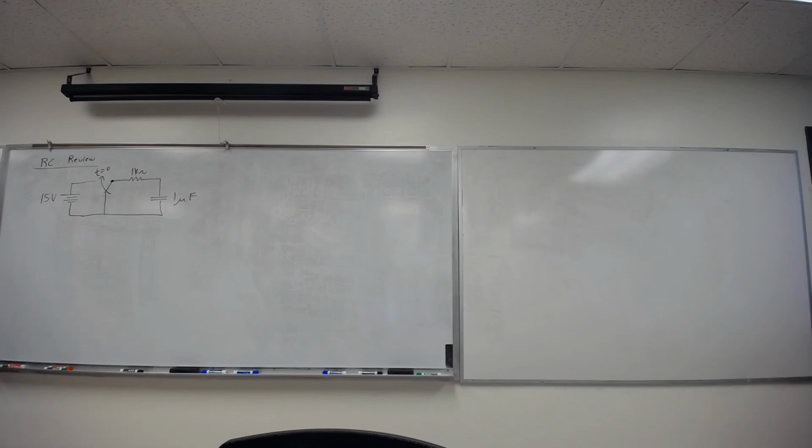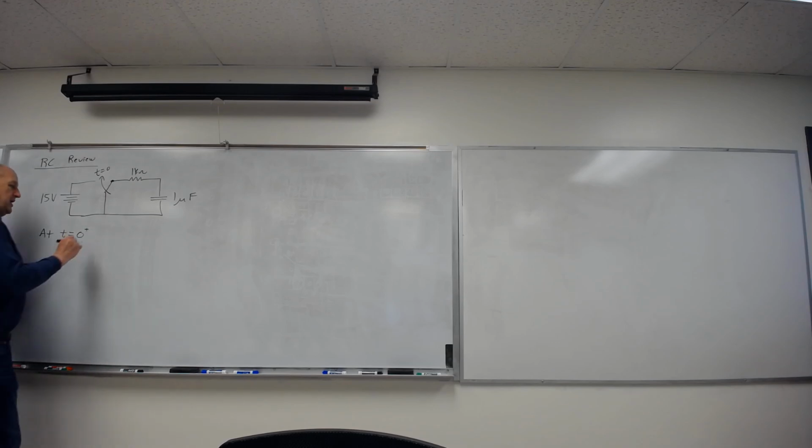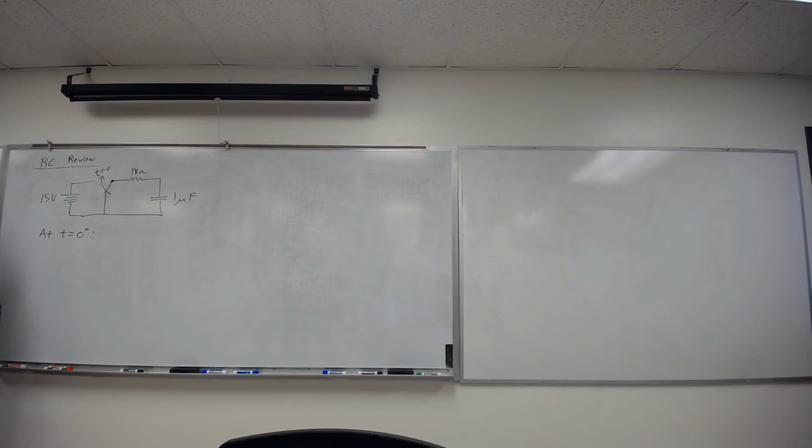Quick snap questions. At t equals 0, a lot of times mathematically we'll put a little plus. So t0 minus is the instant 0 when it hasn't connected, and t0 plus is the instant 0 when it's connected. So I have a complete circuit. What things happen here? Okay, capacitors don't allow an instant change in voltage, right?